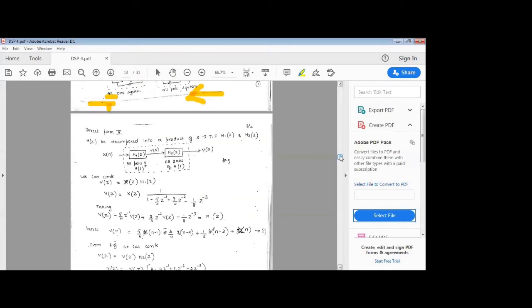In the direct form 2 structure, we combine the delay elements required for the poles and for the zeros, so instead of twice, we reduce it to once. Depending upon the order, the same number of delay elements will be required for both the poles and the zeros.